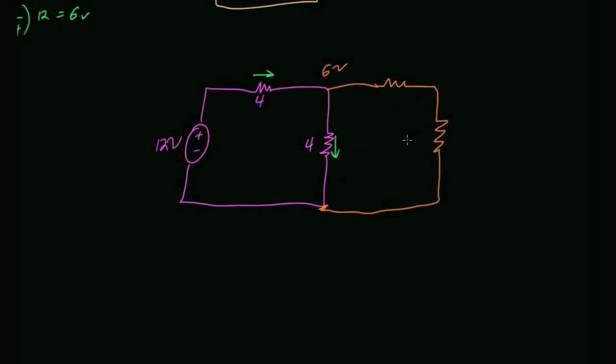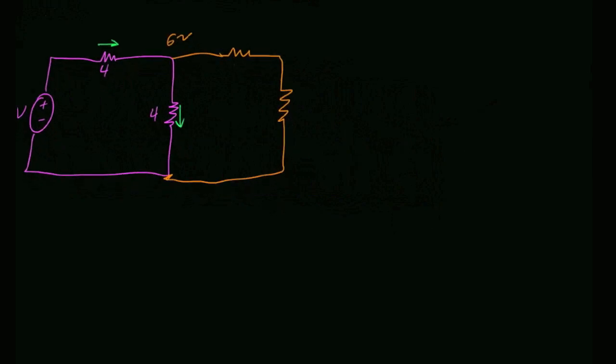Will that make that resistance go up or down? So in other words, essentially what I'm starting with is a 4 ohm resistor, and now I'm going to put some other resistance with it in parallel. So this is 4, and this is whatever I'm adding in parallel. If I put some other resistance in parallel with that 4 ohms, let's think about the range of values that could happen. Can this parallel resistance ever be more than 4 ohms?